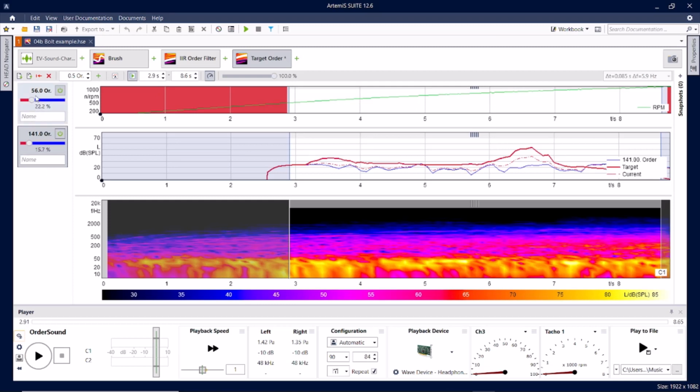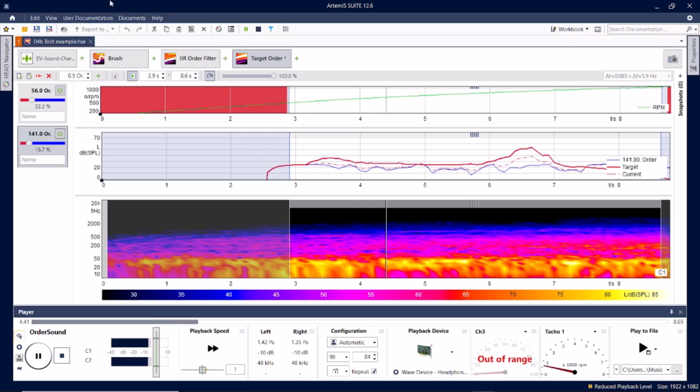So we have, for example, the 56th order relative to wheel, and the 141st order relative to wheel. We could calculate those. I think it's 8, 12, 16, and 20 or 30th orders relative to E motor RPM at that ratio. So here's the sound with the modification.